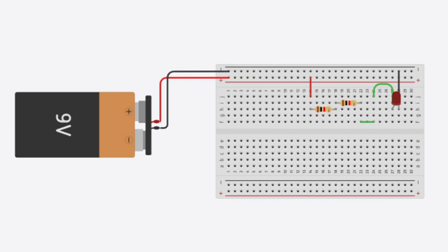Step 6. Calculate total voltage. For voltage sources in series, the total voltage V total is the sum of individual voltages: V1 plus V2 plus Vn. Step 7. Calculate current. Use Ohm's law: I equals V total over R total to find the total current flowing through the circuit. This step will help you analyze and prove the characteristics of a series circuit.